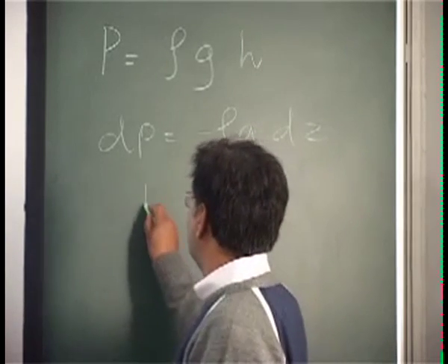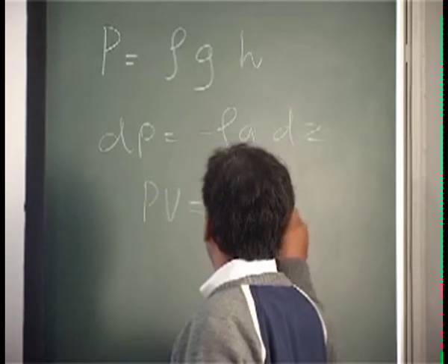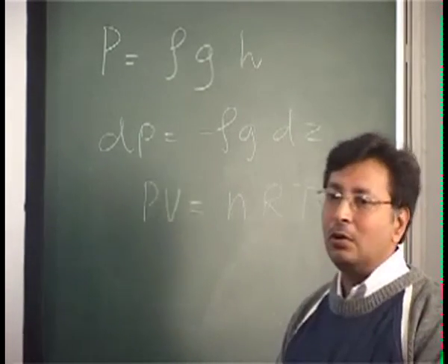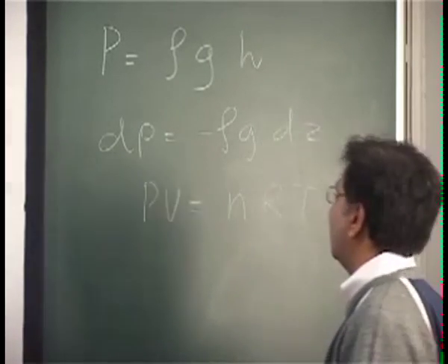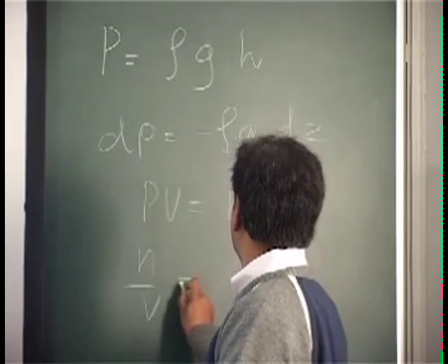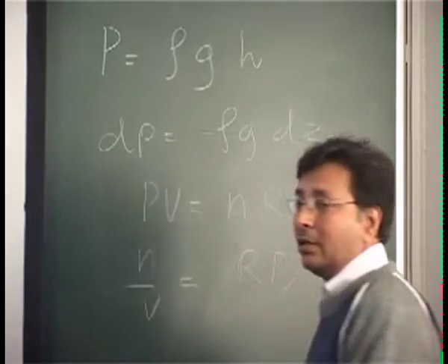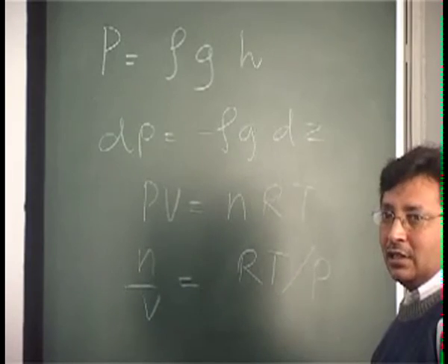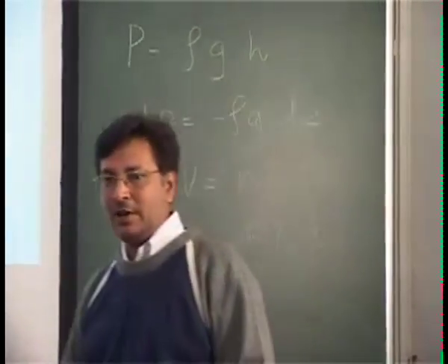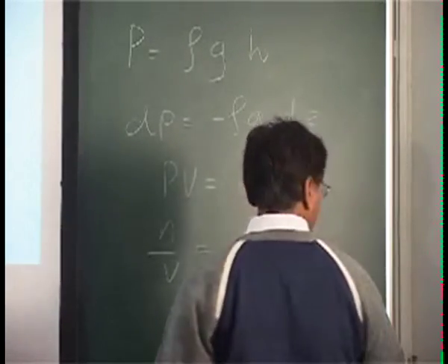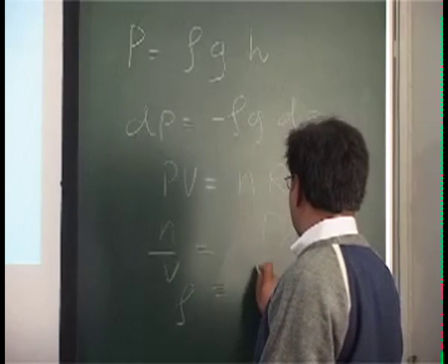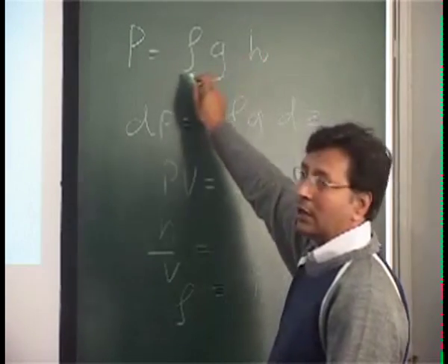So if you look, this we will use maybe hundreds of times: the universal gas law, PV equals nRT. What is n? The moles, or mole fraction, or whatever you like. Can I find out the rho from here and try to replace the rho? I can make mistakes, so be careful. So can I say that? This becomes P by RT. Okay, we can replace here.